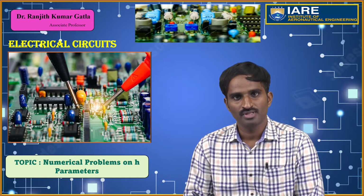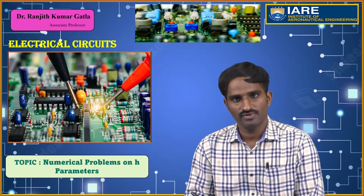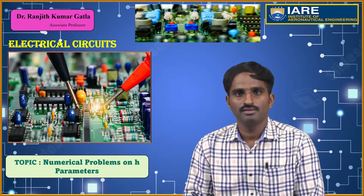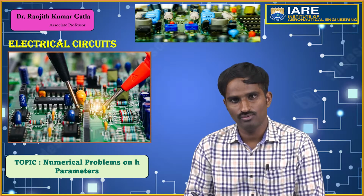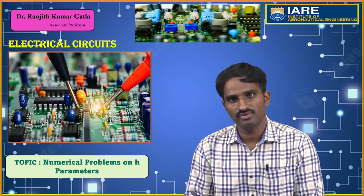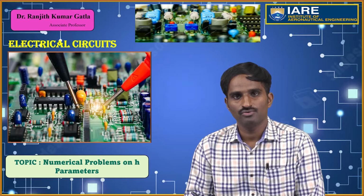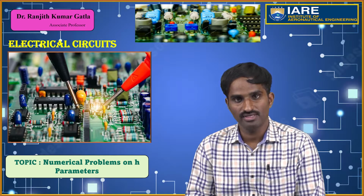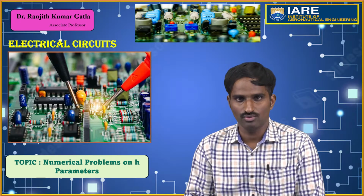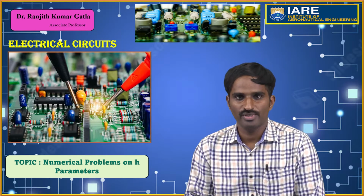If you want to find the Z parameters, in the first case, to find Z11 and Z21, we make I2 equal to 0, which means we make the output terminals open circuit.